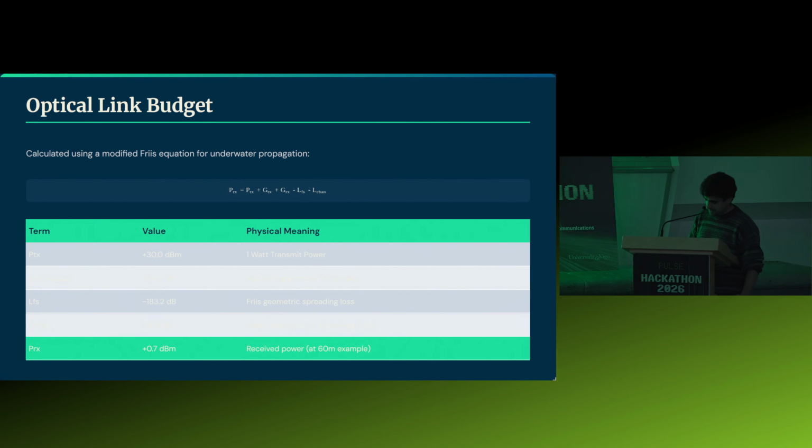Okay, for the link budget, what we did, I don't know who helped us with this, is to assume initially we are in free space optics and use the standard Friis equation, and then add our small angle approximation water channel loss, which is obviously different from the negligible loss you have in free space. Things we had in mind for the link budget: you have to apply corrections for some things. For example, you have to apply some decibel penalty for the fact that it's not a single mode transmitter. It's a wide beam, so you're going to lose some of the signal. You cannot think that the lens is going to focus all of the light directly.